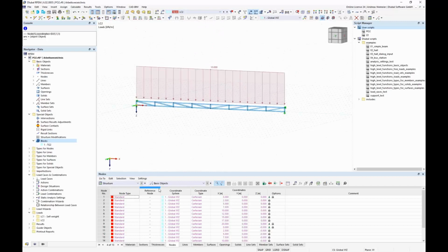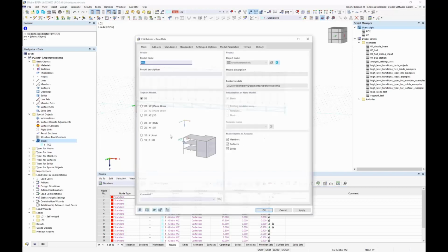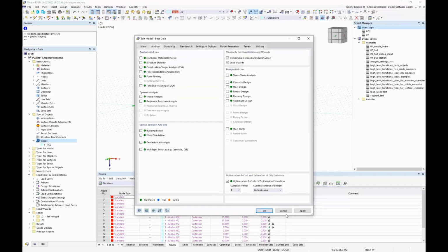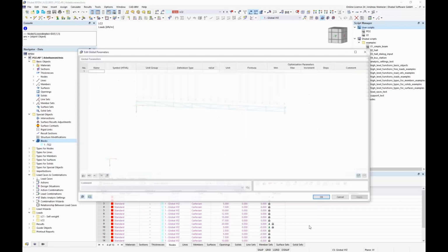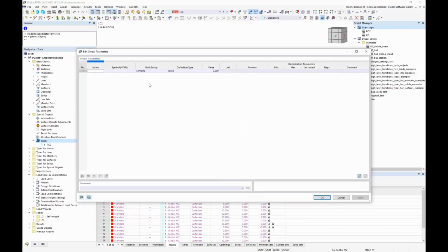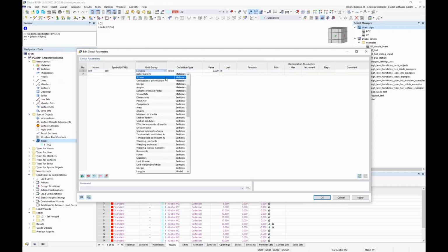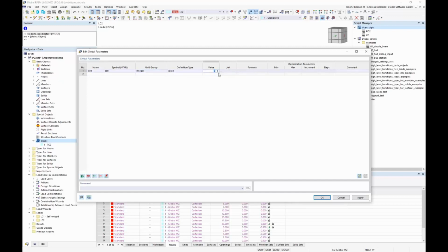And now we can connect it to the optimization. So we connect here our optimization. We specify here our parameters, for example, cell, which is maybe an integer value. So we go here to model integer and write, for example, 4, and because it's an optimization variable, we say it should run from 4 to 10 with an increment of 2.